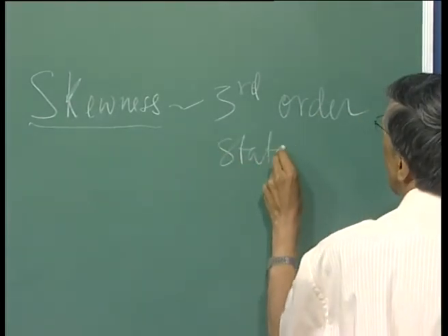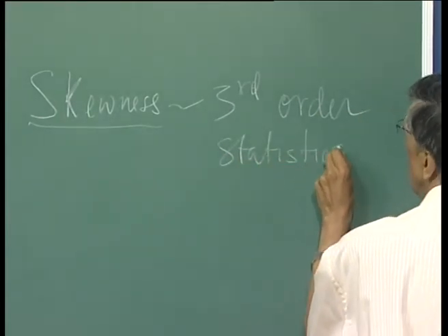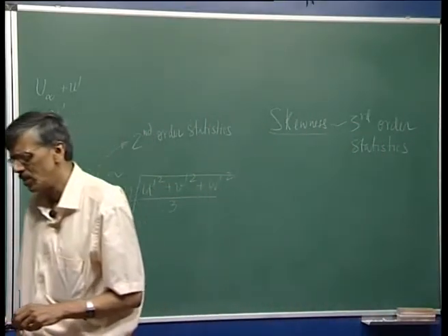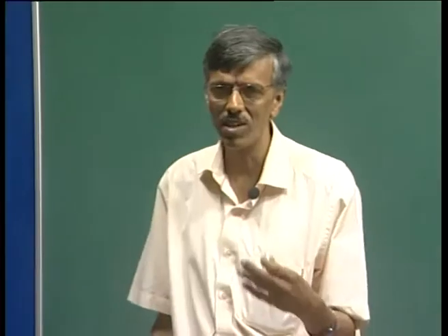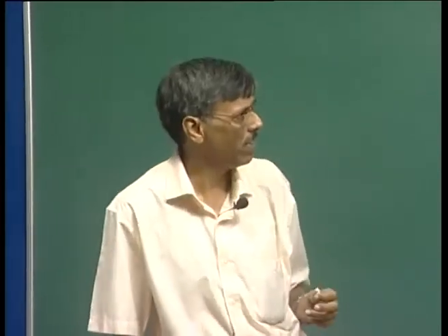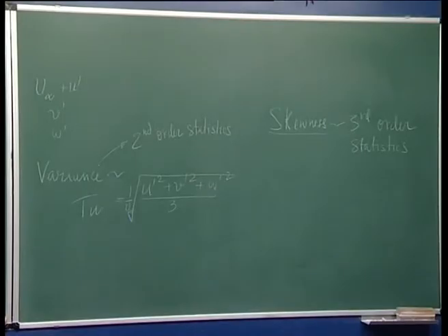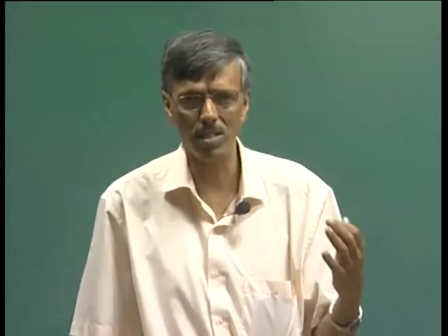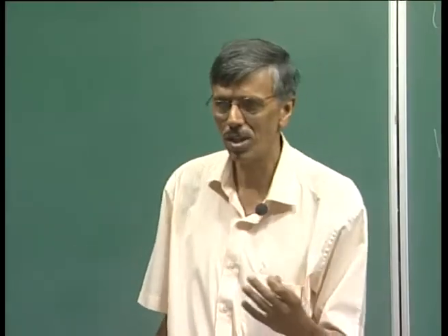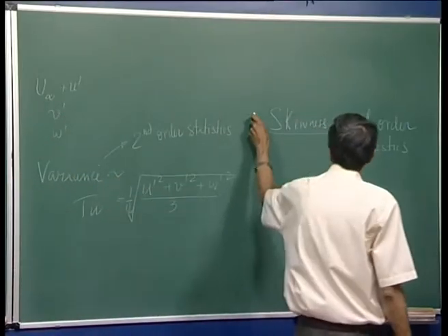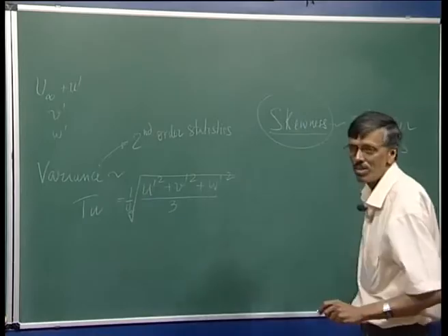It has been shown long ago by Batchelor and Townsend that even if you are looking at, say, homogeneous turbulence as it is created in an experimental scenario, this skewness is contributed by the instability of the flow, right. So, there is this seed of instability in the skewness itself.